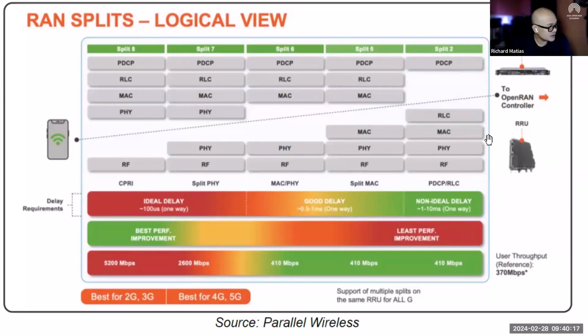And then if you want to deploy more RRUs on site, and you only want to deploy a basic LTE or basic GSM or 3G call, what the experts are proposing is that you only define the RF component in the RRU, and the other functionalities in the CU/DU split, so that you can produce less expensive RRU because the circuitry is very simple.